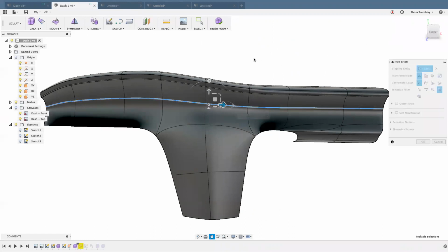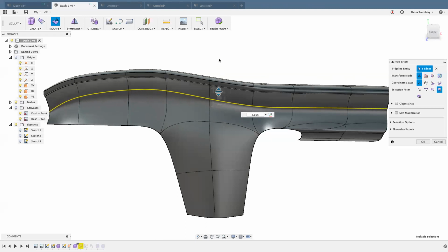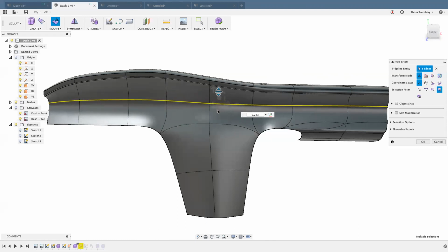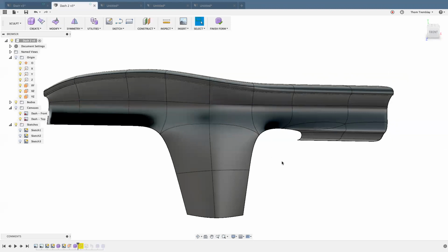Let's take scaling, for example. I'll scale in one direction. You'll see how we can use scale to further add to that curvature, or we can go the opposite direction. In fact, if you type in a value of 0, it will do its very best to make that a straight line. Now, because it curves normal to how we're looking at it, it won't be perfectly straight, but it will straighten it out. So you can use scaling to either exaggerate or reduce the curvature of an edge.